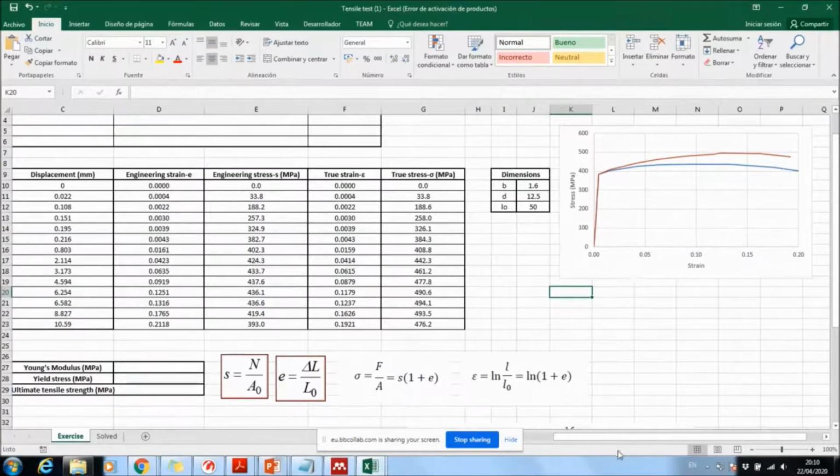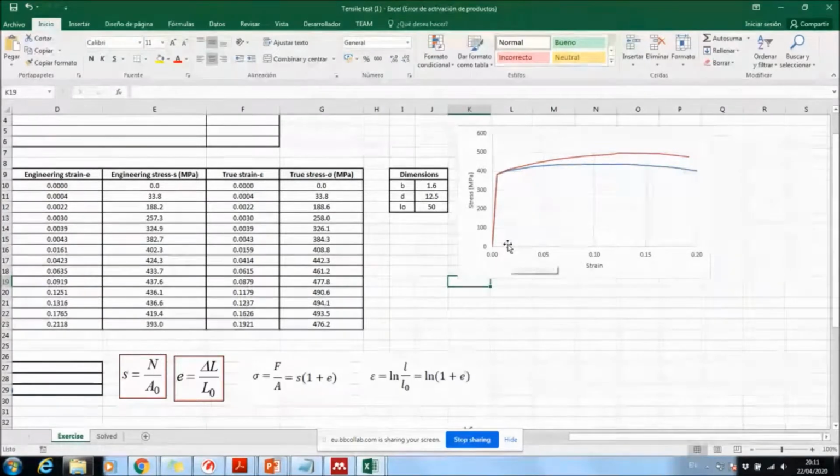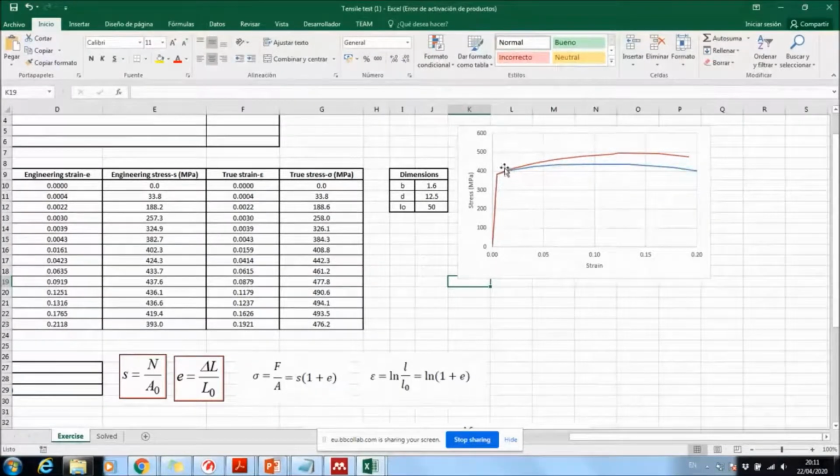And guys, here there is an important thing to take into account, right? The first one is that, as you can see, at very small strains, below probably 2 or 3%, in this region, we see that both the stress, the true and the engineering stress, are almost the same, right? What it means is that for linear elastic purposes, it doesn't matter what kind of stress we're going to use, right? Because they're going to look like each other. There is no big deal.